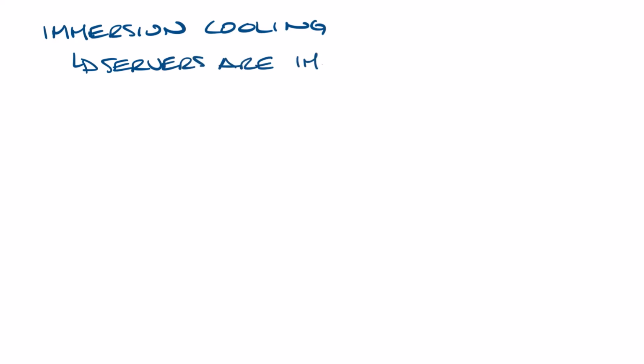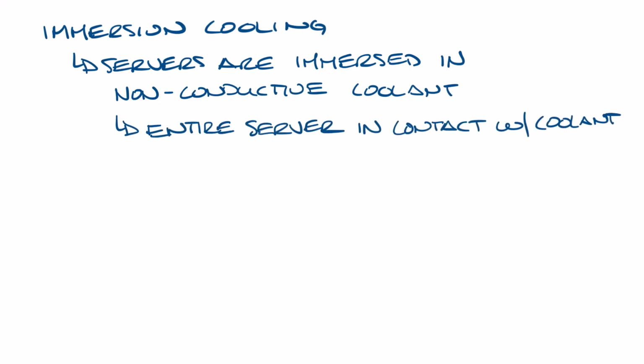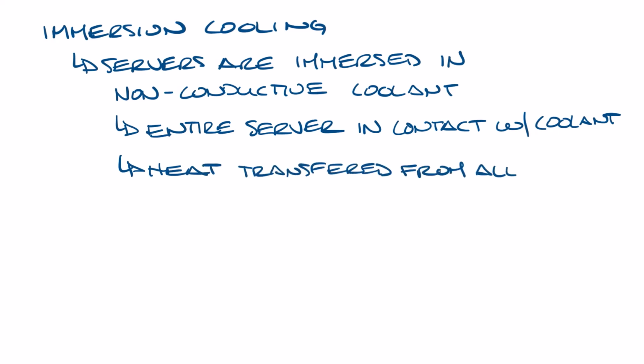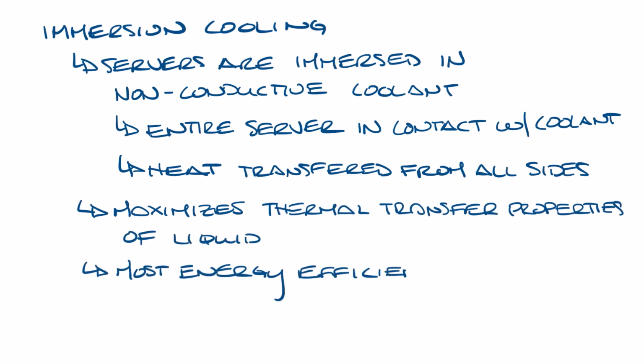Let's slide this up one more time. And then there's immersion cooling. With immersion cooling, servers are submerged in a non-conductive coolant, allowing the entire server to be in contact with the coolant. This allows heat to be transferred from all sides. This maximizes the thermal transfer properties of liquid and is the most energy efficient form of liquid cooling. Now let's slide this over again.